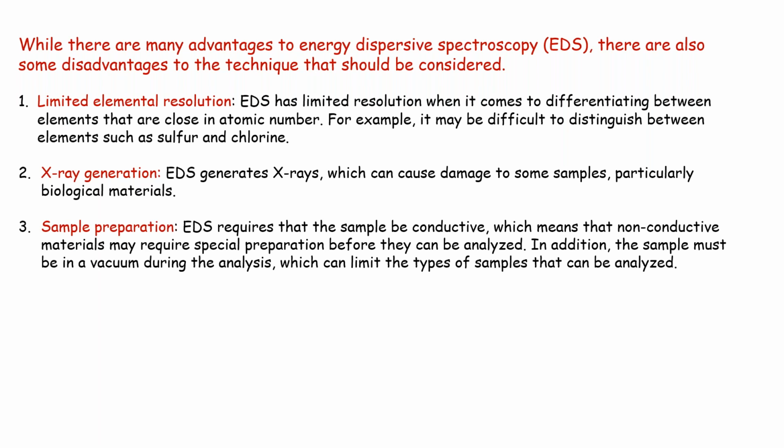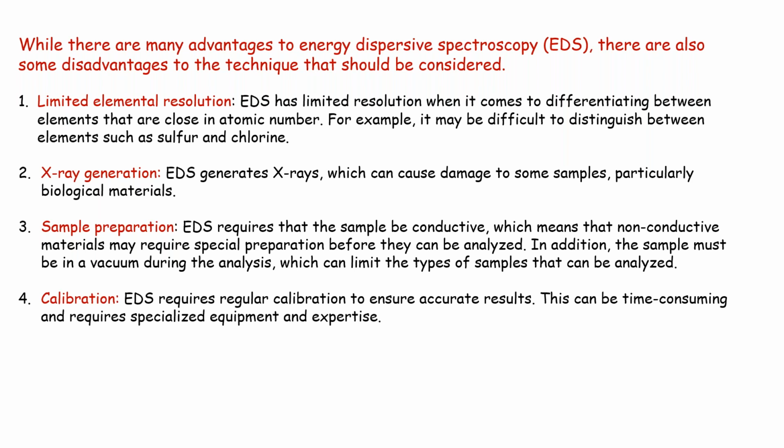And sample preparation needs to be conductive, so some non-conductive samples need some special preparations. And it needs to be done under vacuum, so it can limit the type of sample that can be analyzed. And calibration. This is the major part. EDS requires regular calibration to ensure your results are accurate. It could be time consuming,